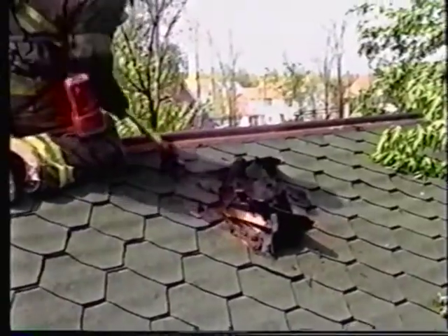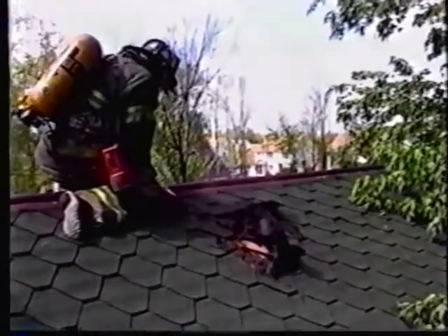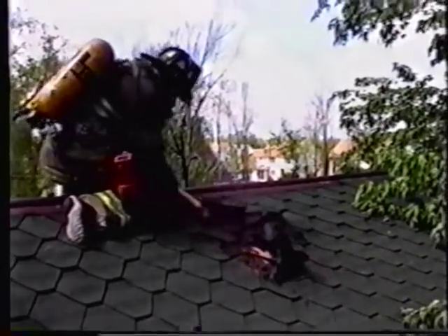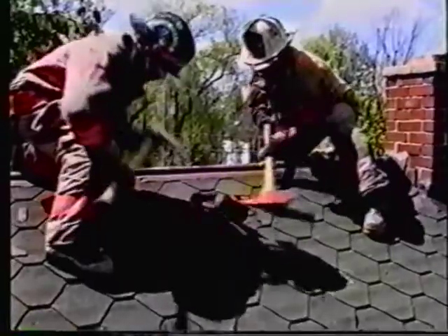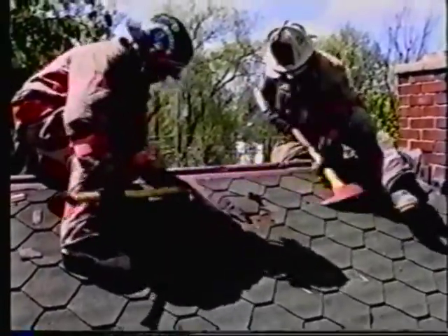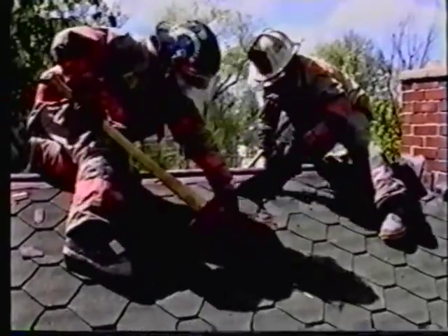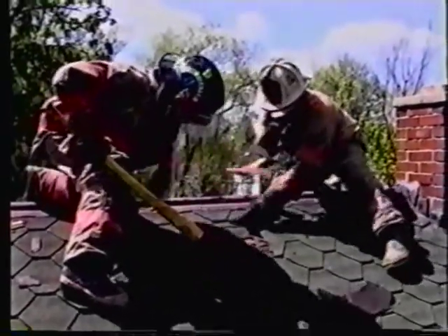Once the location for the hole is selected, use the blade of the axe to remove shingles in the area of the cut. Tiles or slate will have to be broken to be removed. Remember that personnel on the ground could be injured by sharp falling tile or slate. Again, communications. Removing the roof covering will expose the roof deck and allow you to determine if the decking is plywood, boards, or particle board.